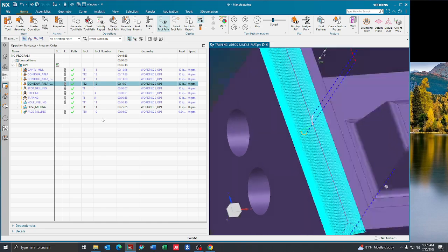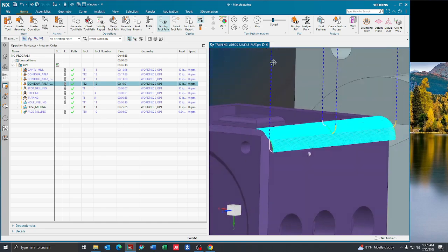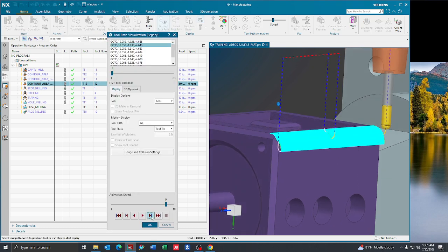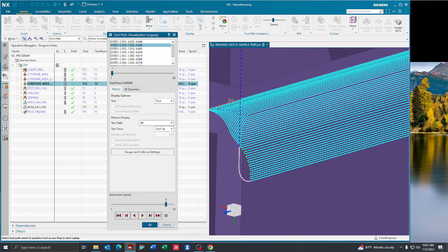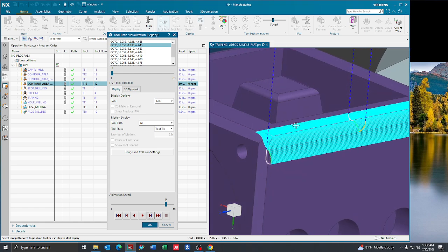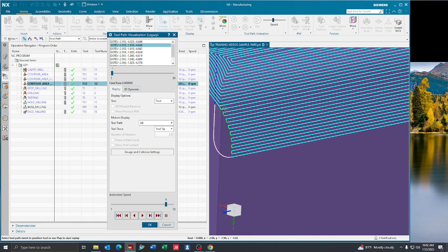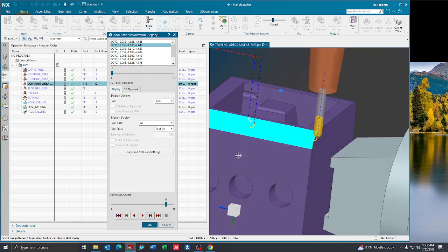And here's a good example of using the steep and non-steep methods in this toolpath. Coming square onto the part, you will see that the top is a different pattern than the bottom, transitioning right here where you have these green lines. The top is our non-steep follow periphery cut pattern, and this bottom, where it overlaps, changed to steep with the zig.